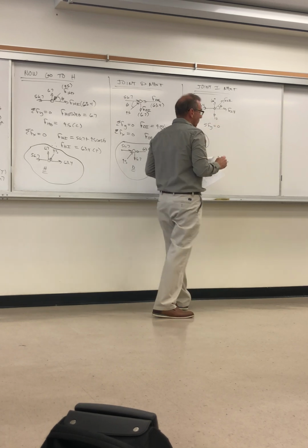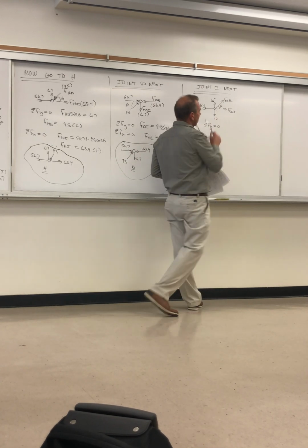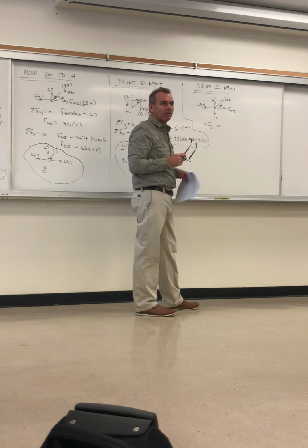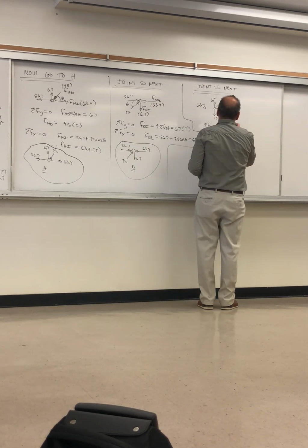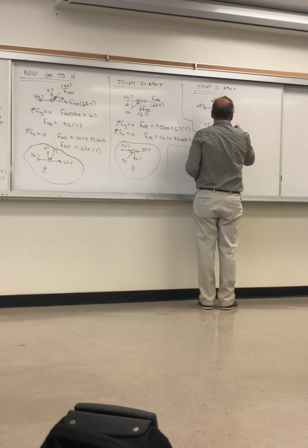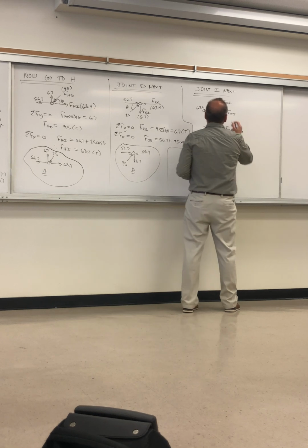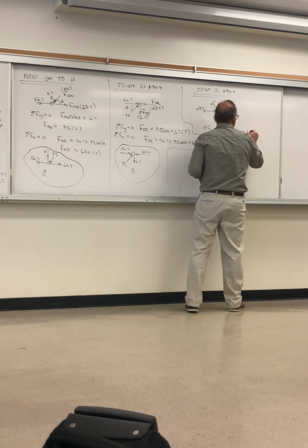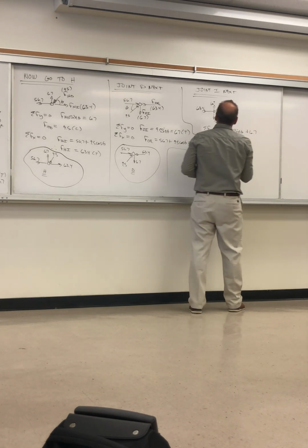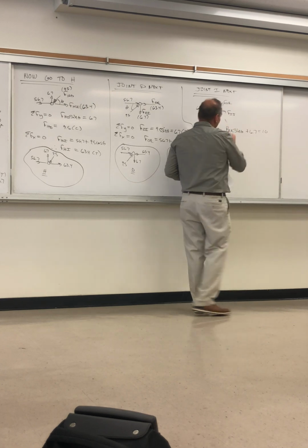Summing forces vertically, you have to be a little careful, the 6.7 is up, and the vertical component of F of IE will be up too. So you have F of IE multiplied by the sine of theta. This is the unknown I'm solving for, so that's the vertical component of that, plus 6.7, in the same direction, equals the 10 going the other way, right?